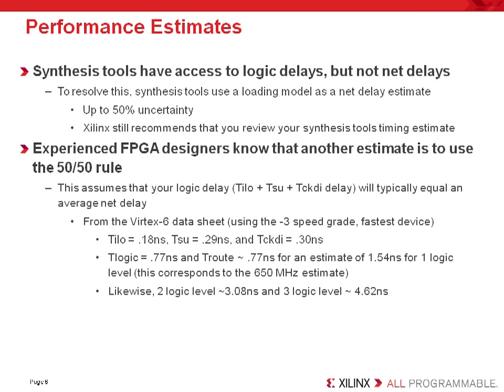But the key thing to note here, that's one logic level. When you make this model map to two logic levels, that's two LUTs in series, so we go register, LUT, LUT, and then go to another register, it equates to around 3 nanoseconds. Three logic levels is over 4.5 nanoseconds. And this is why it's important to understand that you have to code with minimal logic levels if you expect to achieve peak performance.